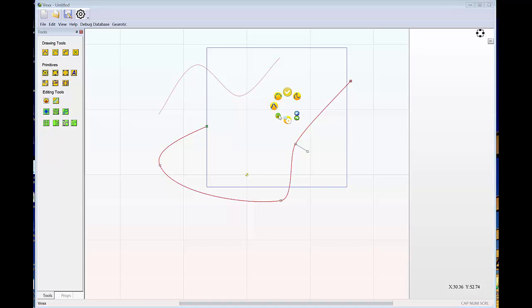Now at the same time on the screen, I'm going to go back to the scissors here. You can see that a control key and 2 shift keys have appeared below. This is to indicate to you that these are modifiers that can be used. If, for example, I hover my scissors over this end of a Bezier curve, you can see that it intersects with the square and it knows it would trim it right at the beginning of the square. That may not be what you might want, however.